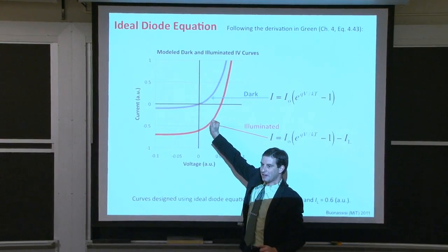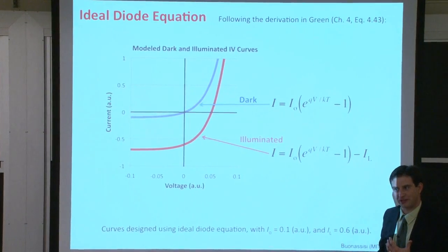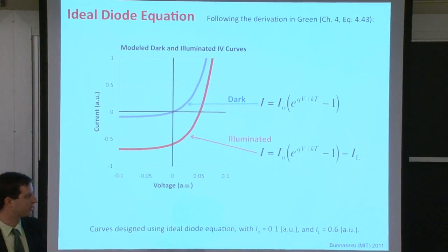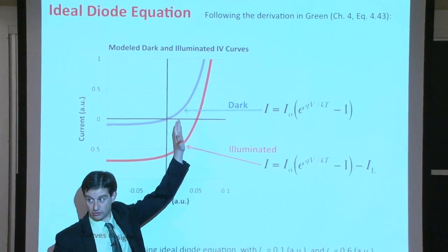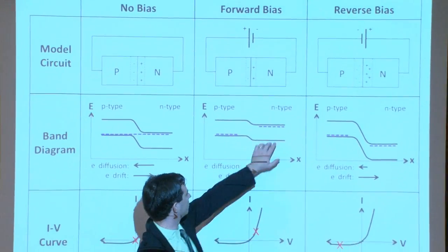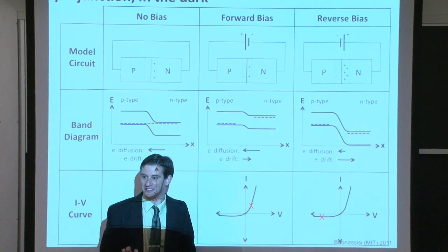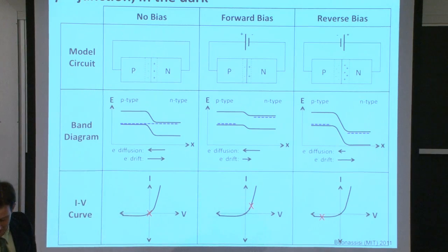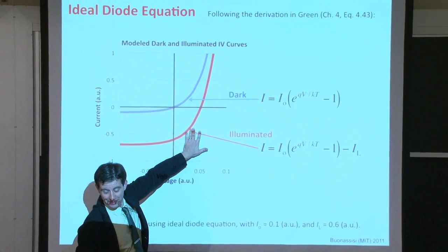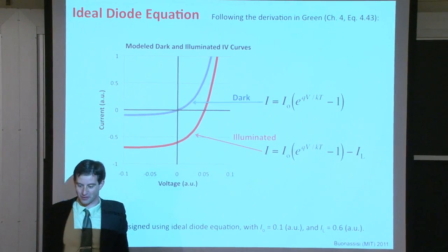So we're beginning to develop an intuitive understanding of where electrons are flowing inside of our solar cells, in the dark and under illumination. The dark is important because we can test our devices in the dark, and we can still learn a lot about our solar cell device characteristics. As well, under forward bias conditions in the dark, we can force carriers from one side of the junction to the other the wrong way and probe for weaknesses in the pn-junction region, so that's helpful. And in the illumination condition, obviously, we're testing the total amount of power that's coming out of our device. So again, this is very useful because it's off of this red curve here that we define the efficiency or the performance of the solar cell.